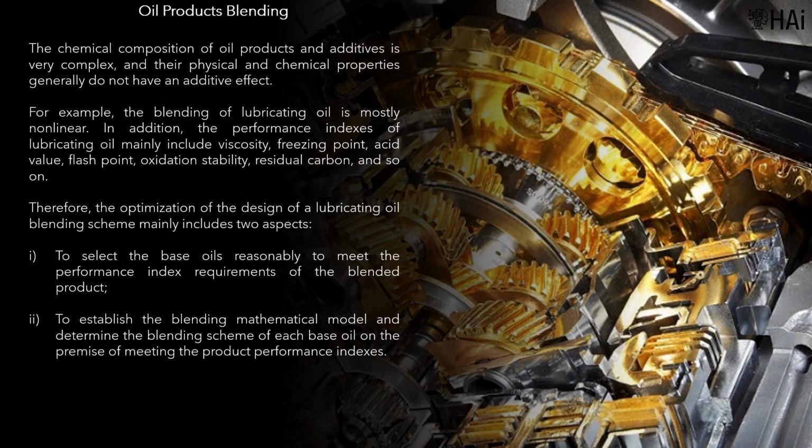The chemical composition of oil products and additives is very complex, and their physical and chemical properties generally do not have an additive effect, so the blending of lubricating oil is mostly nonlinear. In addition, the performance indexes of lubricating oil mainly include viscosity, freezing point, acid value, flash point, oxidation stability, residual carbon, and so on. Therefore, the optimization of the design of a lubricating oil blending scheme mainly includes 2 aspects: